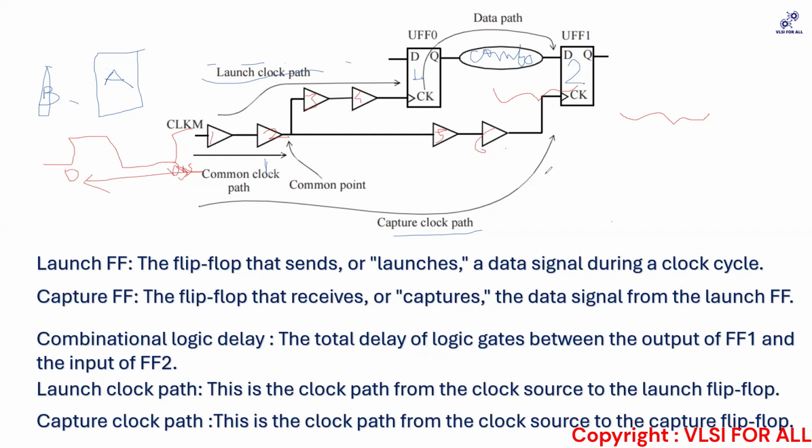Okay. So now for this, we understood that the clock skew is nothing but the difference between the capture clock path delay and the launch clock path delay. Now, the capture clock path, let us say all of these buffers that are there in my design are having a 1ns cell delay. Okay, so now let us calculate it. So how much will be my T capture delay?